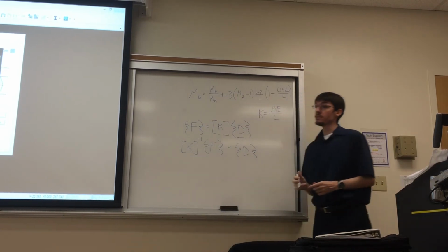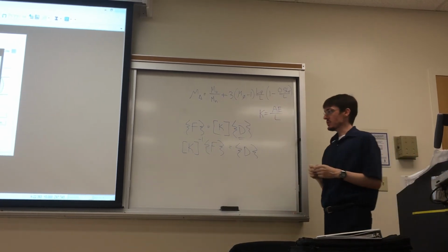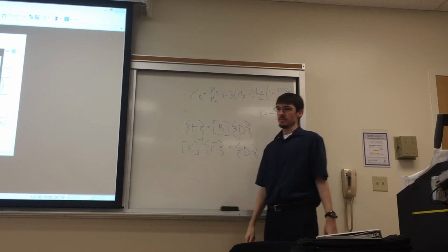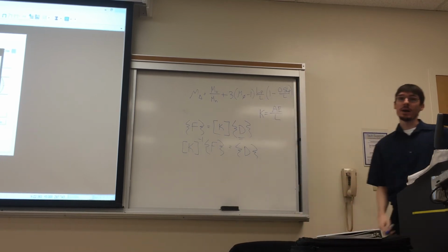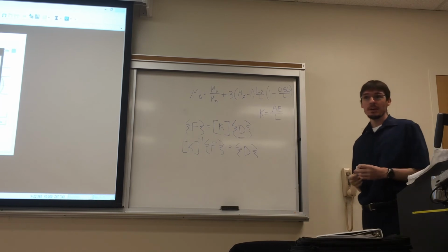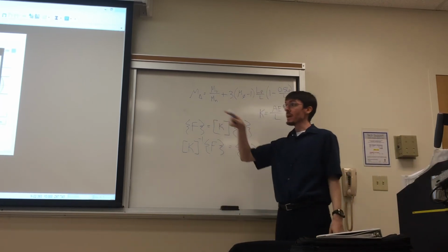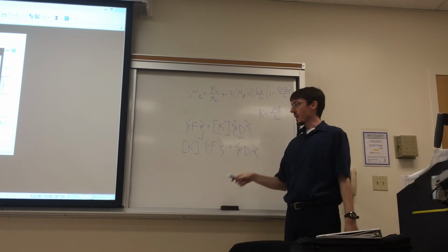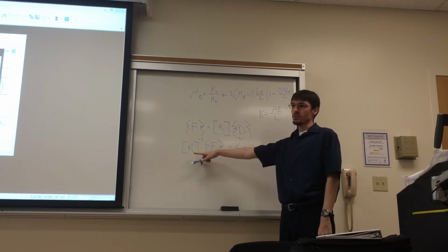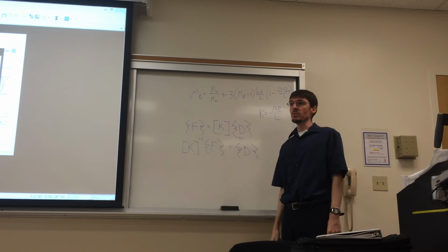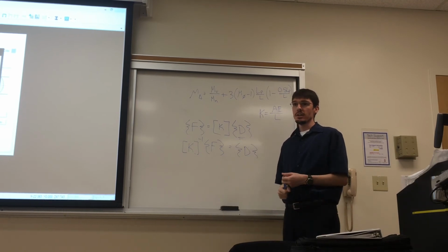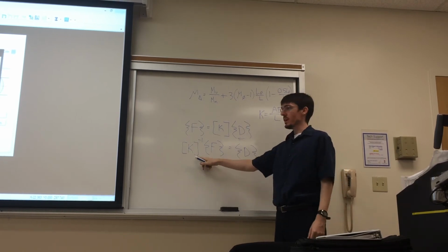So you have to be very, very mindful of this. What happens when you invert matrices? Potentially lots of things. Right? That's why you have, let's say, a background in calculus coming into this sort of stuff, because you have to be wary about this. If you have, let's say, really big disparities in values, i.e. you make one of these stiffnesses way too big, what can happen is you won't ever get convergence of this matrix. It tries to invert this matrix, one of the numbers is way too high, and it can't ever reach a solution. And so you may not even be able to run your analysis if you make this too high.